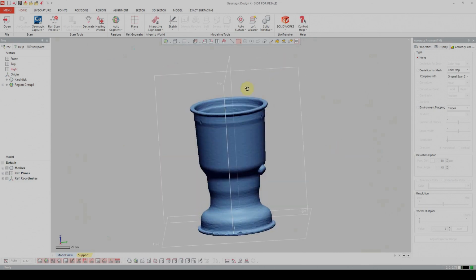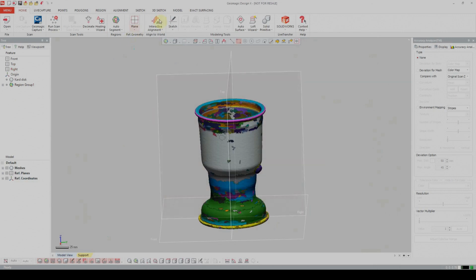These base planes will help me cut this mesh apart so that I can see inside of this spot and extract my reference sketch. But I still need to find an axis which is an intersection of the top and right base planes, because this axis is going to be a reference axis for the revolving part. I'm going over to the Model tab and hitting the Vector button.